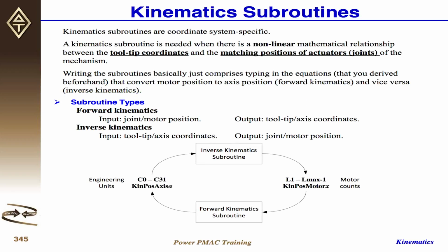Okay, before we get into the kinematics section, we have a linear setup, we call it axis definition. We already talked about that in the motion program. So you define one motor to a certain axis, in a specific coordinate system. So there are two levels. First, you have to specify which coordinate system you want to work in. The second is you define one motor to one axis that belongs to that coordinate system.